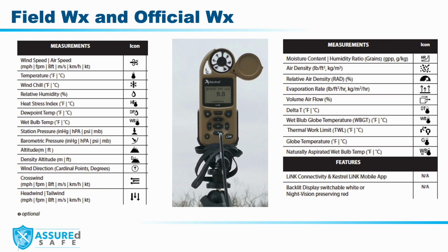Official sources of weather show measurements that are mainly forecast unless there are reporting facilities at that location or nearby. Measurements include sky conditions, current and forecast weather activity, temperatures and pressures, as well as hazards. They are also prescribed to a much larger geographical area than a typical UAS operation would cover. Therefore, for UAS operations, it is a good idea to gather more localized weather data. In the field, weather meters can provide much more timely and accurate data. This real-time weather information will enhance the decision-making capability of the pilot and therefore the safety of the operation.